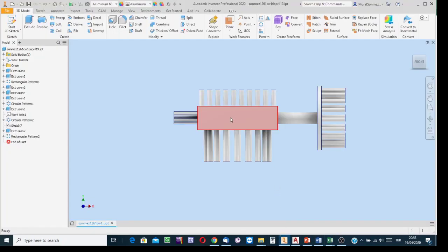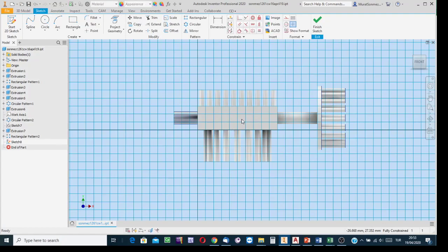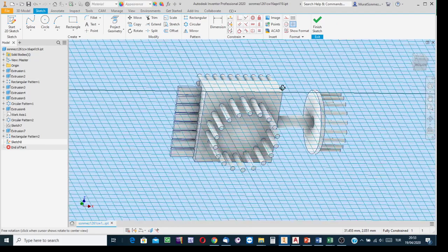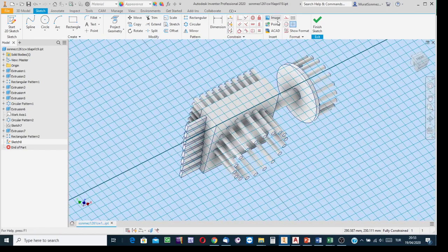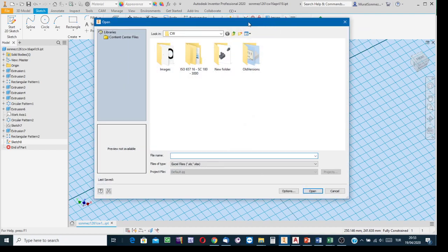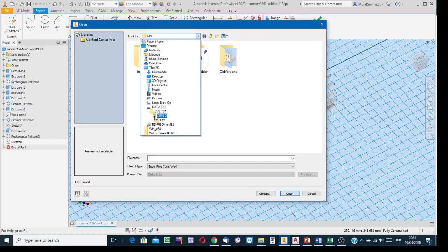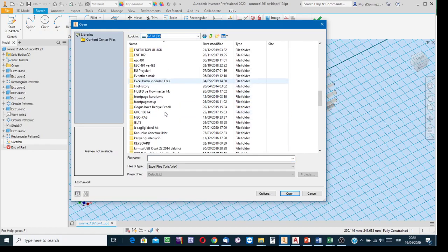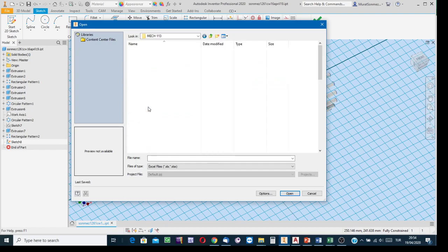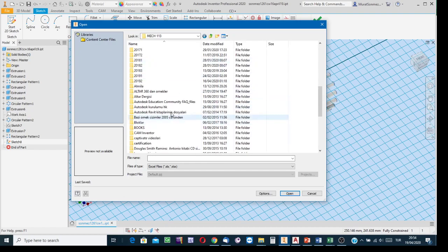I'm going to import the Excel data over the surface. Take a sketch right over the surface. Okay. And then in sketch mode, yes, here is the button to click. Insert not an AutoCAD file, not a picture photograph, but insert Excel data. Click on this button and then start the process. And then in the dialog box, show the address. Where is the Excel file in which I have XY values of the necessary points?